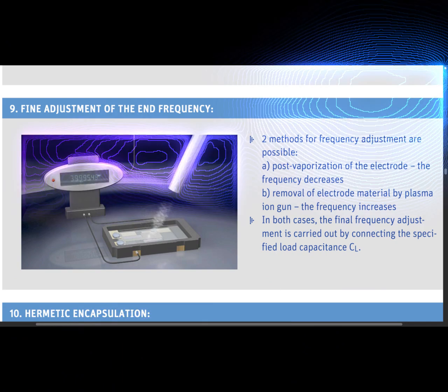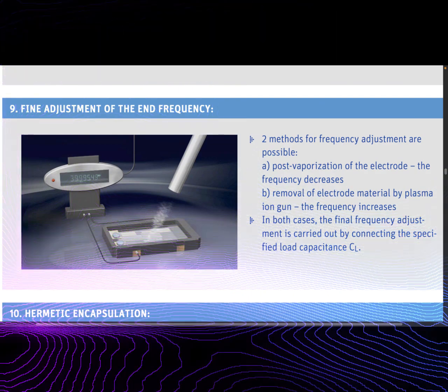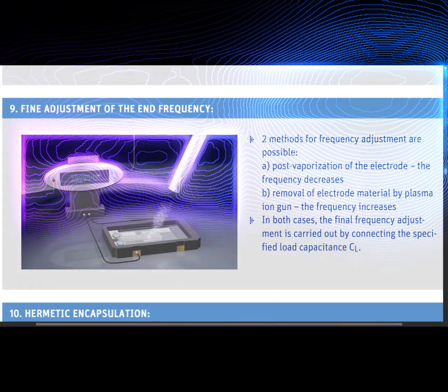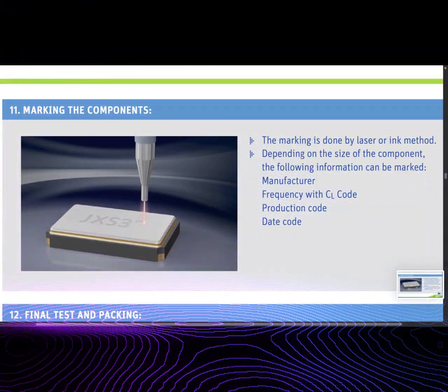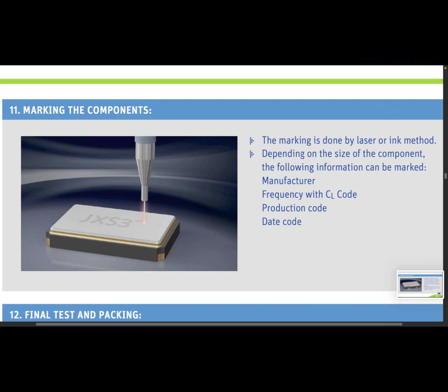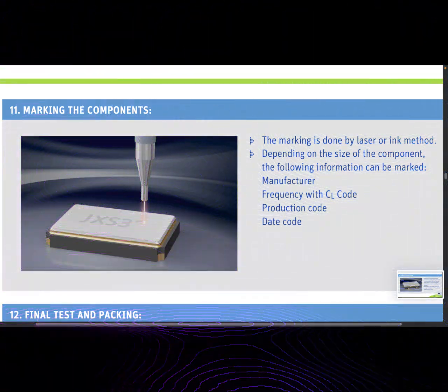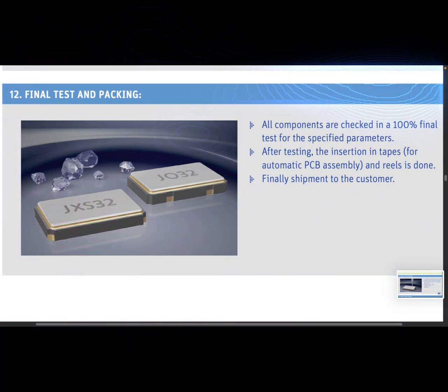It also increases RF phase noise. Pullability, the amount by which the crystal's oscillation frequency can be pulled from natural resonance by changing the load capacitance. This is important for variable frequency oscillators.